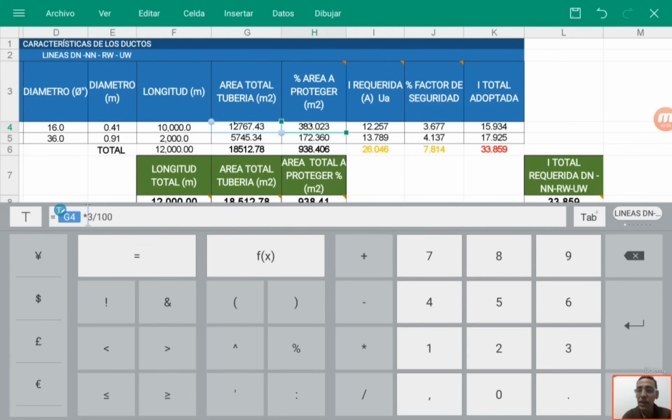Here it is, which is this one right here, 3,000 square meters. Now let's look at the required current. In this example, the pre-required current is 32. What happens if I set it to seawater and put 80 milliamps? Let's see how the current requirement changes now. It went from 15 up to 39 amps, so notice how the decisions you make significantly impact the design.